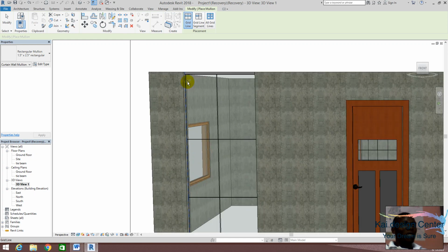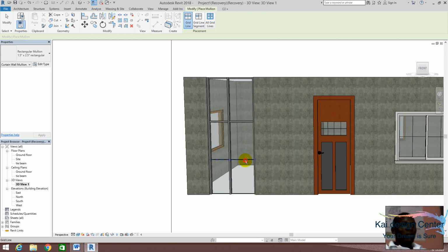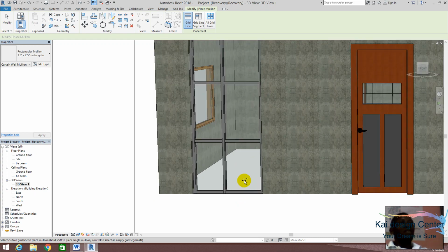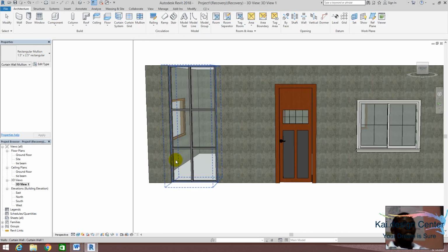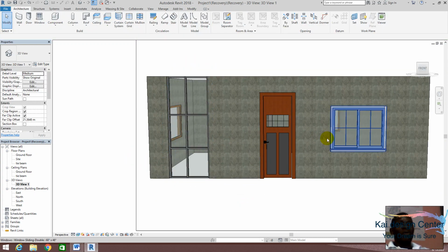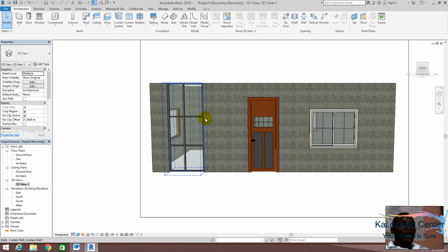So you just pick the element, you click on the areas that have been separated, it will automatically generate. That is it. So you see that we have already created two kinds of windows: the normal window that is fitted, and with the help of our curtain wall, we are able to create another window here, a window from down to top.